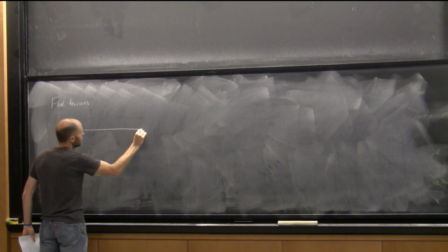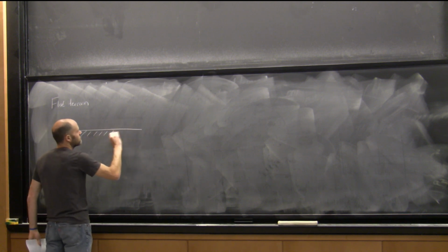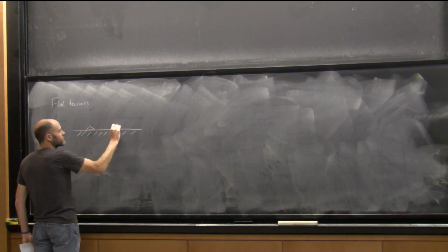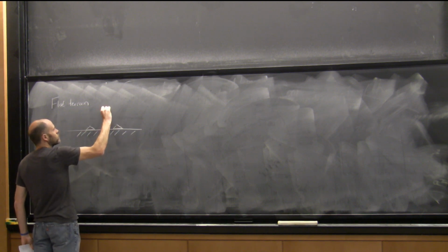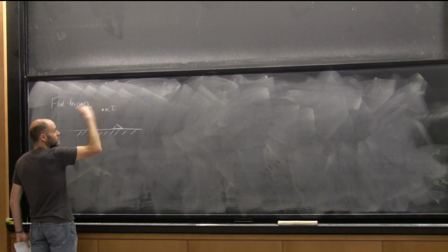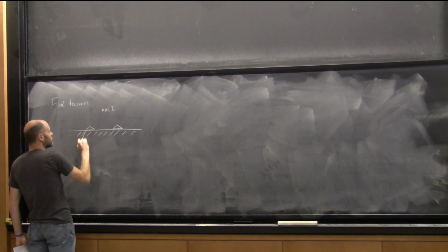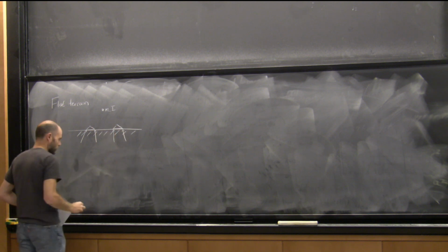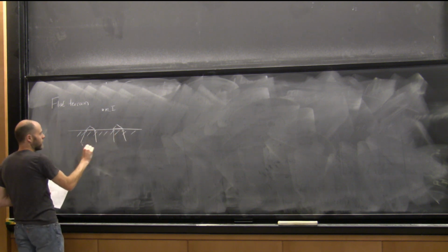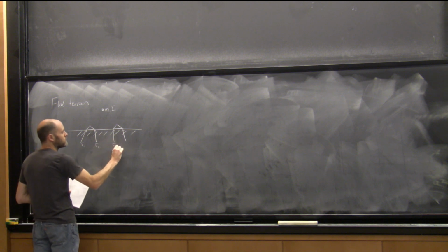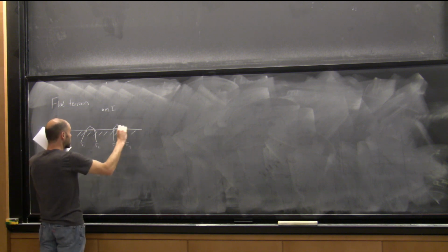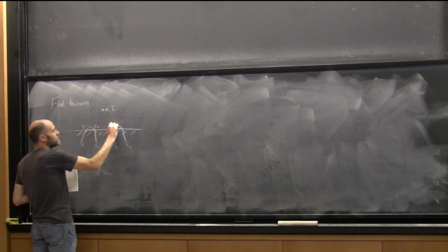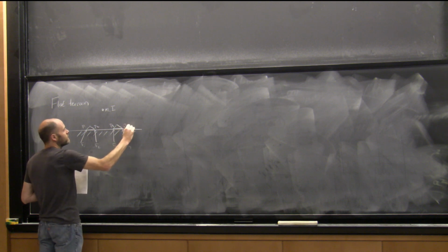If I have a handful of points, a foot over here and a foot over here, and I'm trying to control my center of mass and its effective inertia with some ground reaction forces here, say those forces are F1, F2, F3, F4, and their locations P1, P2, P3, P4.